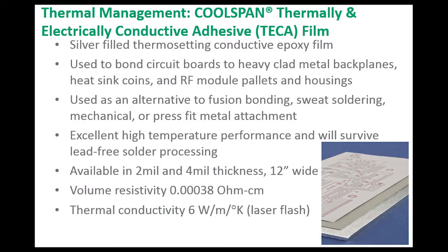The Rogers product CoolSpan is a thermally and electrically conductive adhesive system that will allow you to adhere a circuit board to a metal plate to drive heat out at much higher levels. You can see a thermal conductivity value in the range of 6 watts per meter per degree Kelvin, as compared to values of 0.5 to 1.5 for PCB materials. Typically available in 2 to 4 mil thicknesses, you can adhere the ground plane of the circuit board onto a metal surface like an aluminum surface to drive away the heat.